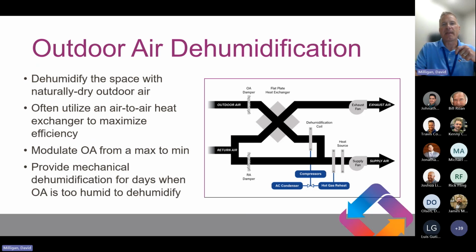We might need to put some type of compressorized system in there to handle a cooling load to maintain space temperature, really depending on what type of sensible loads you have on the space. But generally, we don't need compressors to run all year round to do the dehumidification.